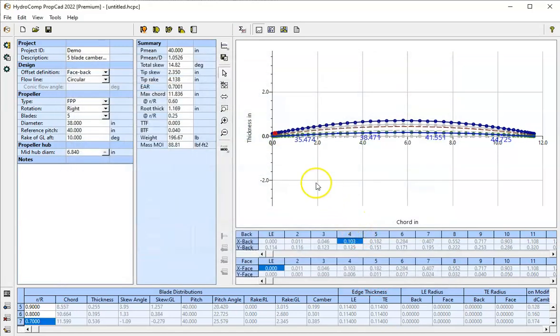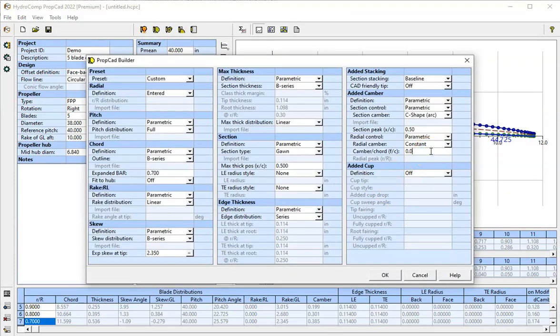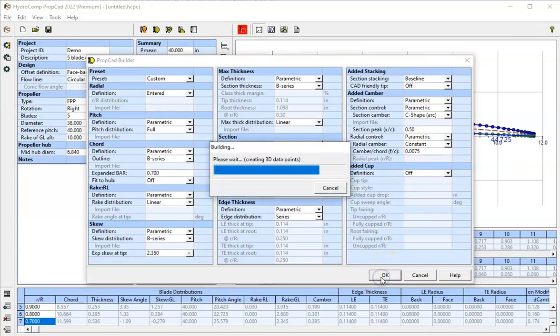When we regenerate our design, now we can see the original shape in gray there, and now our new shape with the camber in there. I'm just going to clear this up a little bit. So here's just our modified shape. We can see here I've overshot our camber, so let's reduce this down. We were trying to hit 38 to 42. It looks like we've got exactly twice as much as we want. So we'll reduce this down to 0.75%. Just a little bit. Less than 1%.